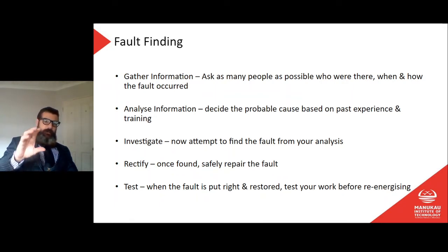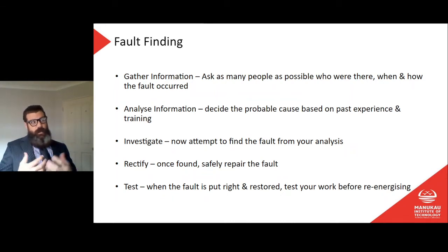And so to me, that gather information is a really important one. It's something I learned in doing that job is, if they say the hose is split and you go there and the hose is split and you change the hose, there's nothing complicated about that. But when you do come across something that's a little bit different and a little bit less obvious, then asking the people what happened is your most important thing. You're going to get a massive variability in the quality of information that comes back. So sometimes you have to take it with a grain of salt.